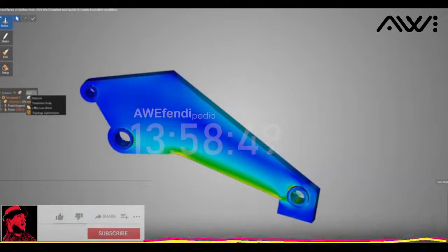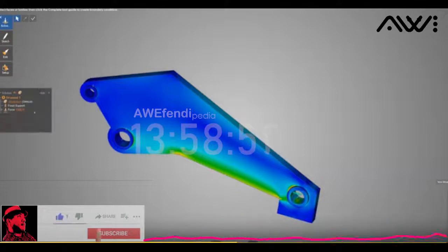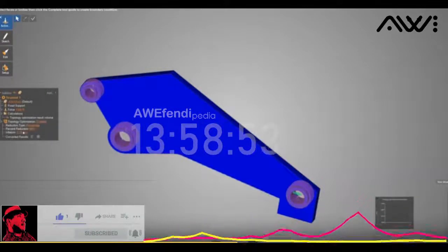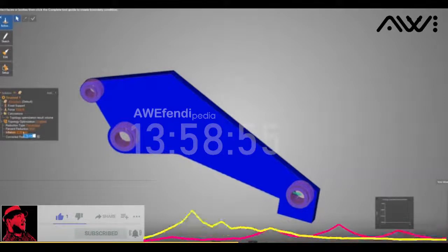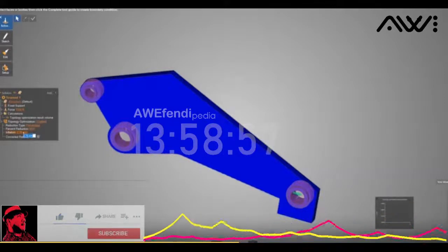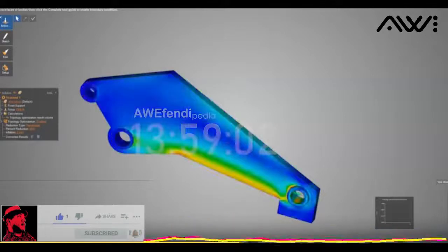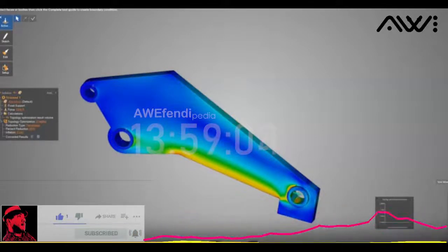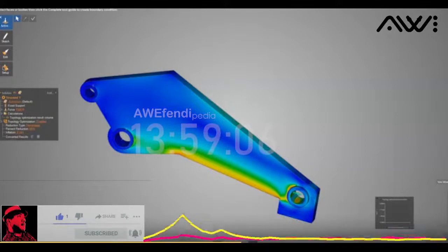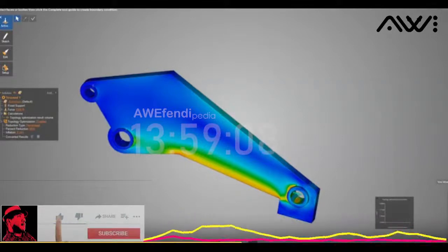So under add, drop down, turn on topology optimization, and it's enabled, right? You can see the inflation rate is a little bit high. I'm going to go with 2 millimeters for now, and we'll go with that. And then now I can just hit play and start seeing exactly what is happening, what type of feedback I'm getting, and then move forward, right?